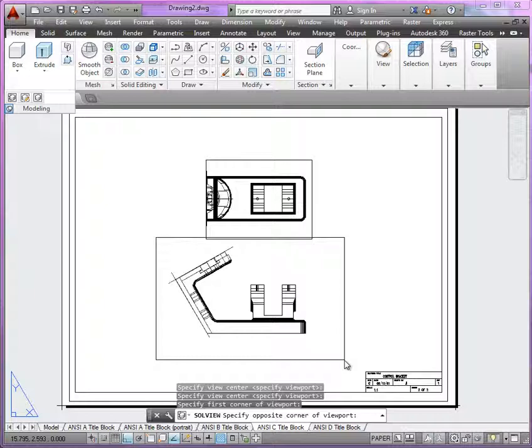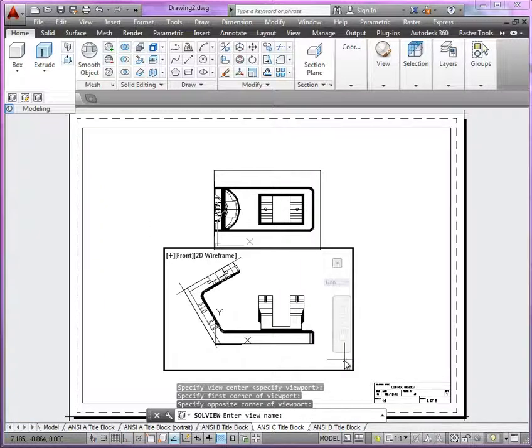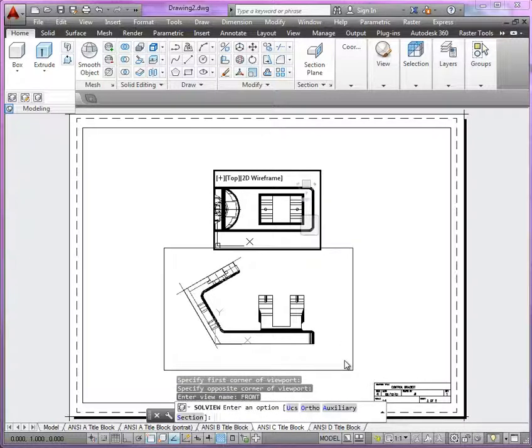Okay. Once you cut the viewport, immediately name it. And it's very important at this point, you guys, not to mess up the sequence. I'd suggest if you have a mistake here that you start from the very beginning. Alright? Because it's going to be important: when you create a layer here, you're not going to be able to remove that layer or rename it later. So this is the front view. I'll call it front. Hit enter, and now we can proceed.